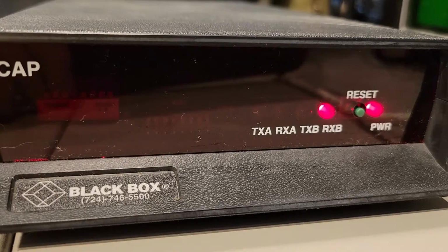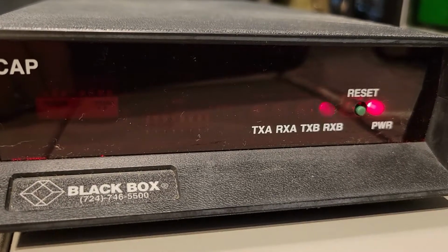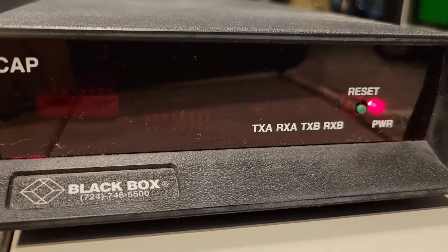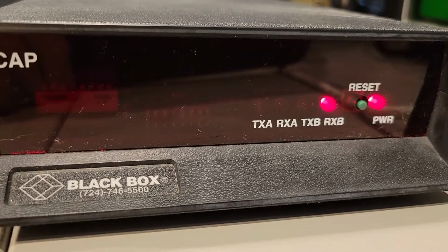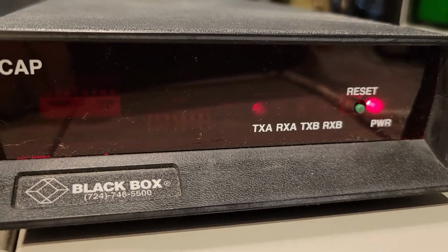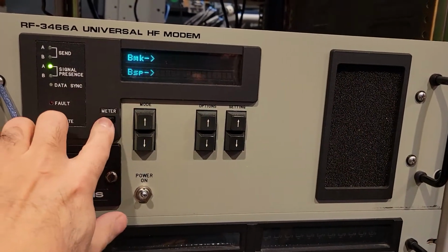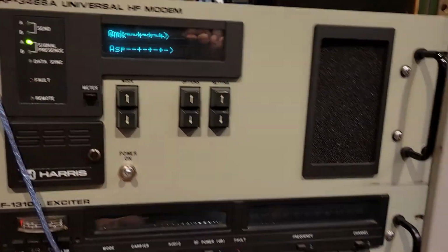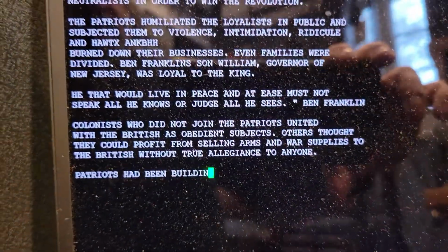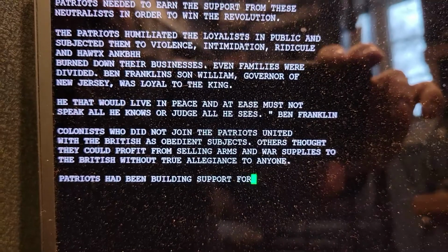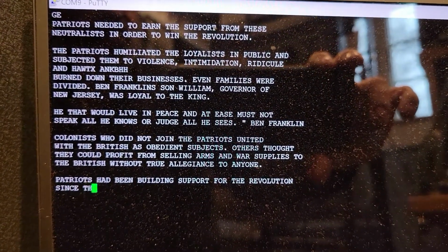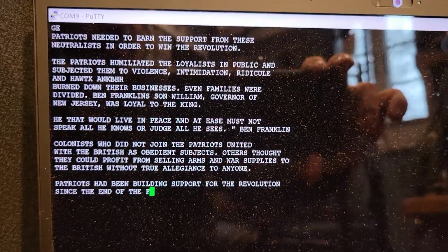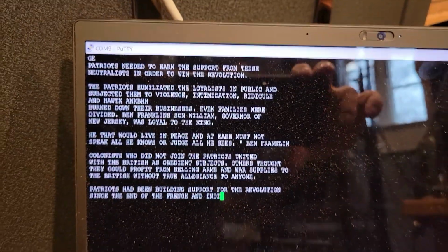TXA, it's port A, the laptop. You see, the A is blinking very quickly, and that's because it's at 9600 baud. So any given character coming in at 45.45 goes out very, very quickly. And that's basically it. That is the receive test. Not much more to show. That is the receive test, working very well. And the next test we're going to do is a transmit test, which is a little bit more involved, and I'll explain why. But overall, this is great progress.